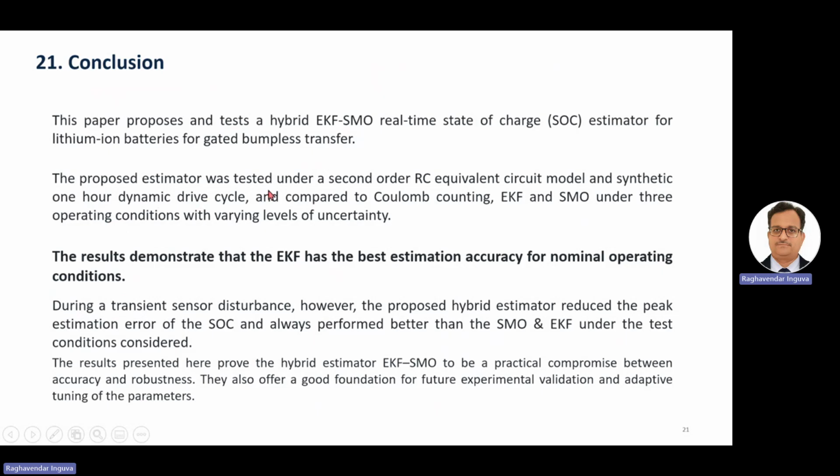The proposed estimator was tested under a second order RC equivalent circuit model under a synthetic 1 hour dynamic load drive cycle and compared to Coulomb counting, EKF alone and SMO alone, under different operating conditions with varying levels of uncertainty. So the results demonstrate that EKF has the best estimation accuracy for nominal operating conditions, whereas under harsh conditions, the hybrid has better accuracy.